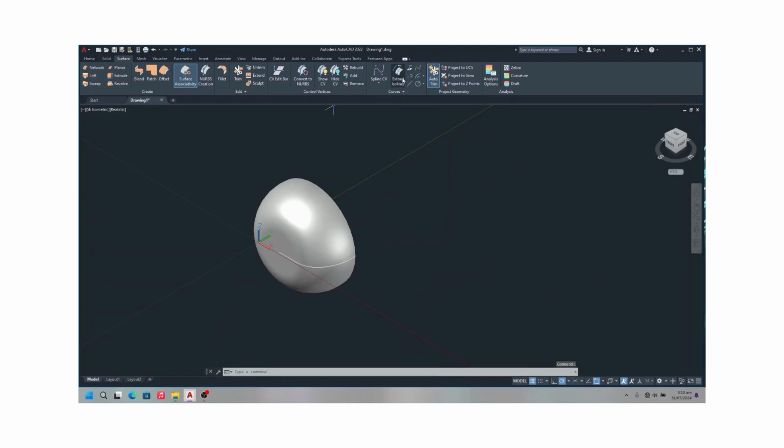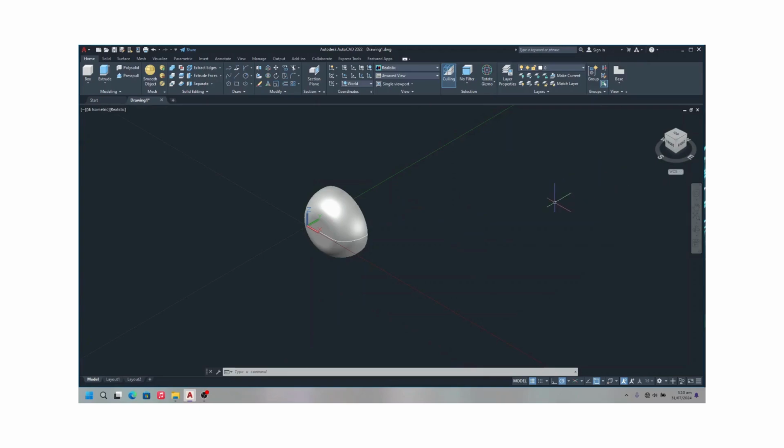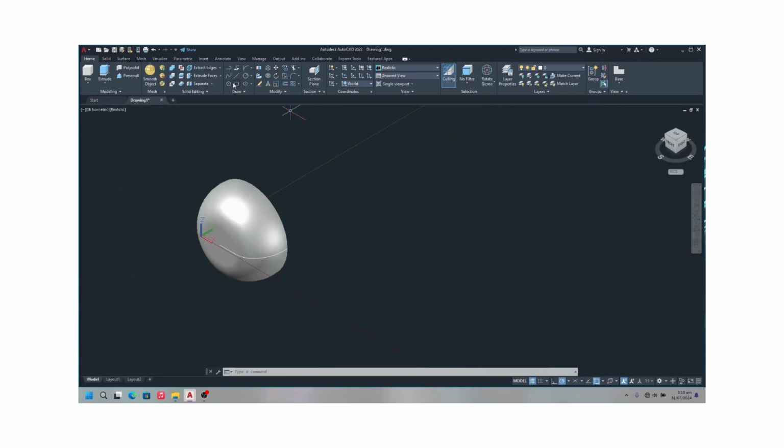Next up, we need to create some patterns. I'm going back to home where I have most of my 2D tools, and I'm gonna start creating just some petals maybe. So first off, to create petals, you need a center point and then an arc. Or in hindsight, you can also use the fillet tool.